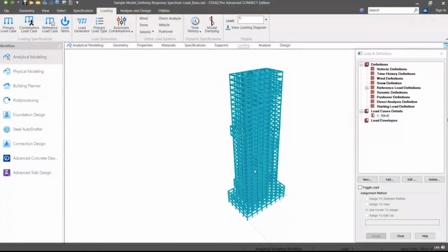First, the modal weight values are reported in 3 orthogonal directions, which is the modal mass times g. For the selected modal combination method, missing weight is also reported. Next are the acceleration value for each mode and damping values. For response vector for all modes, the same damping is considered. The translational and rotational components for modal base results are also reported.